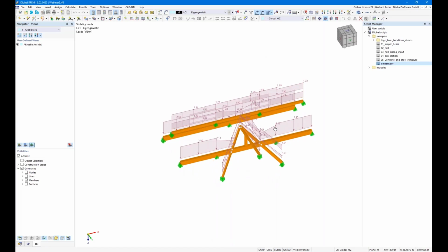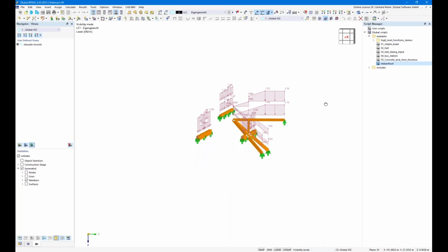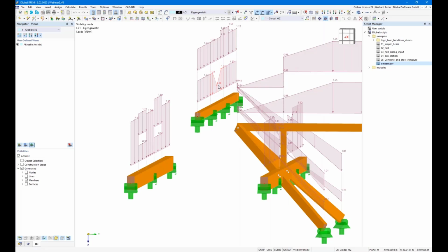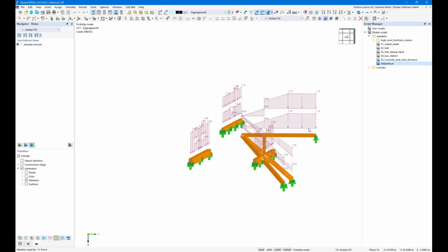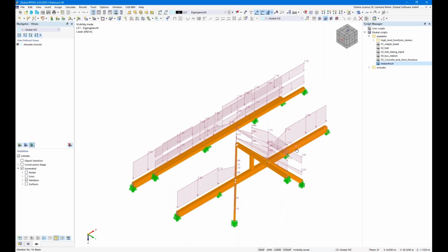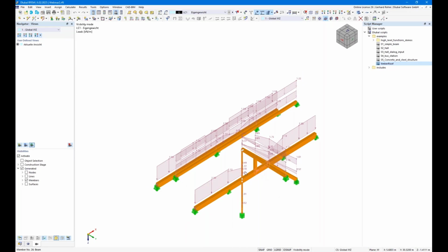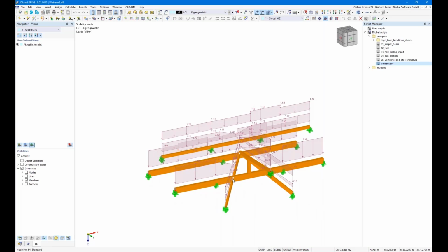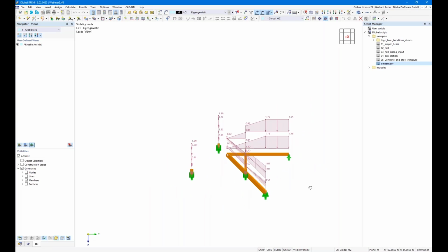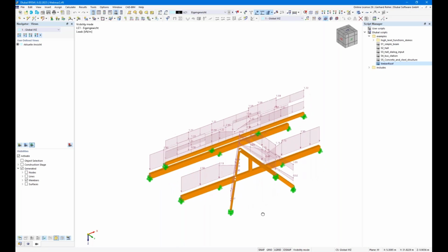So we see the reduction here for the purlin here on the apex, here the reduction because of the hip rafter here, and here we see because of this additional free load, we get more loads on it. And the big advantage here, you can see, I have this semi-rigid support considered here for this hip rafter, because the purlin is not supported here, but here. And this is a kind of, let's say, 2.5D solution.